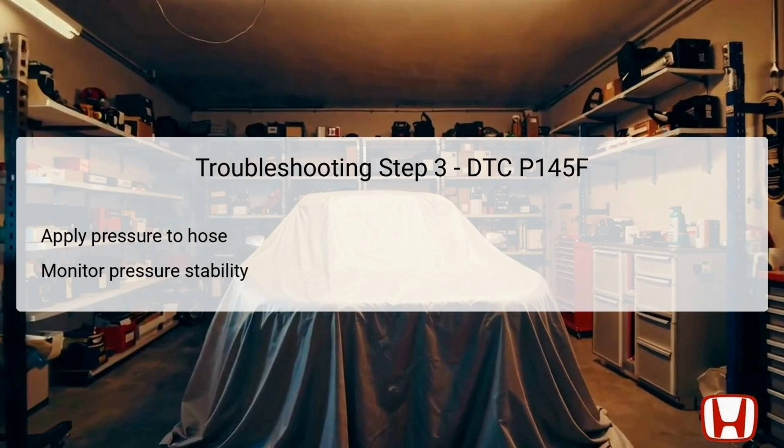It is crucial to understand the expected norm, which generally requires that pressure should not be held excessively. Any anomalies, such as unexpected pressure retention, could indicate problems with the ELCM or other components in the evaporative system. Thoroughly documenting your findings during this process assists in deciding the next steps toward diagnostic resolution.